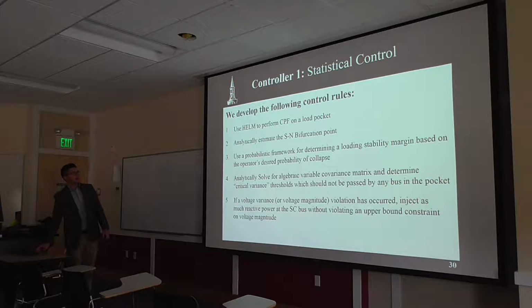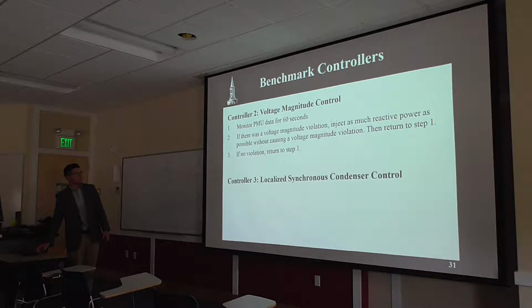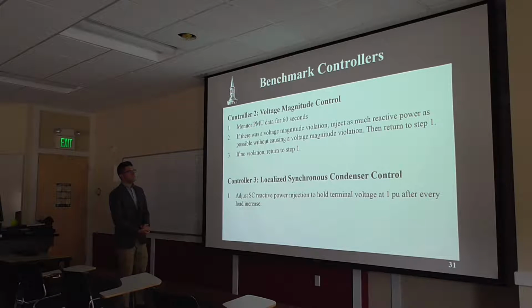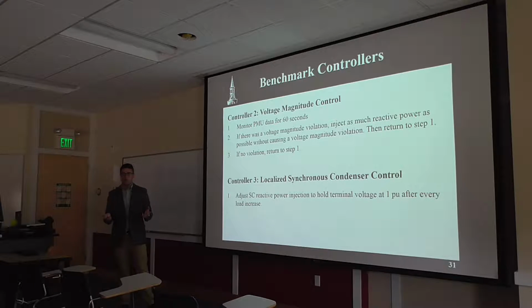In order to assess the usefulness of this controller, we developed two other benchmark controllers. Controller number two, I'm calling it the voltage magnitude controller. Pretty much all it does is monitor PMU data. If there's a voltage magnitude violation, such as if voltage dips too low at any single bus, we have to take mitigating control action, return to step one, continue monitoring.